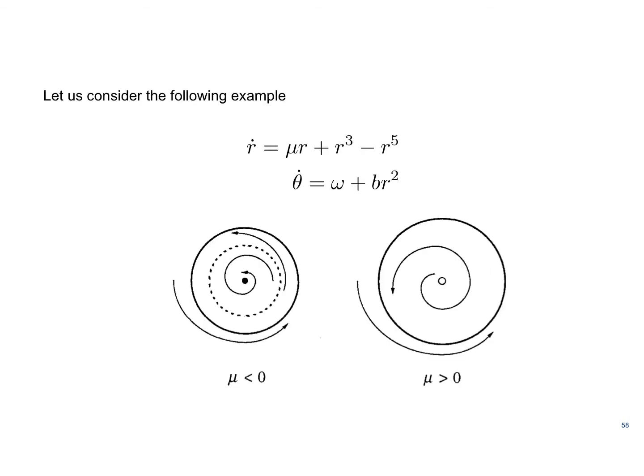We can also have the case of subcritical bifurcations. So remember, these are the dangerous bifurcations, because in this case something that was exponentially decaying, these oscillations going towards amplitude 0, suddenly becomes of very high amplitude. In this example we use just polar coordinates, so r is going to be the amplitude of the oscillation, and then we have these two equations,